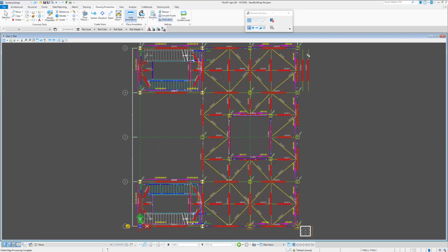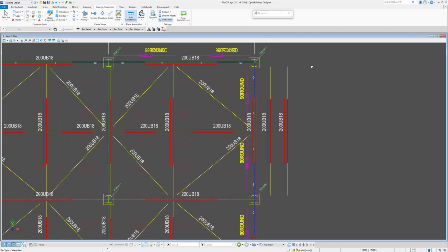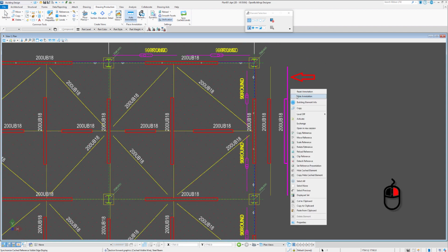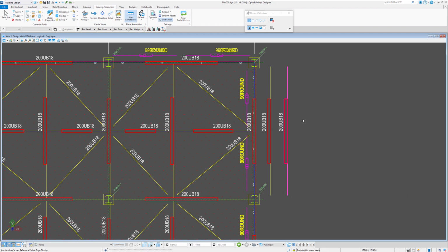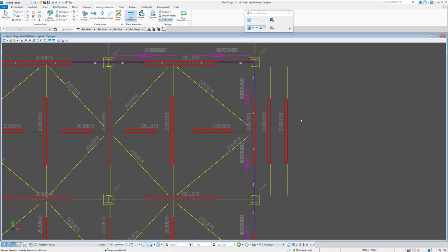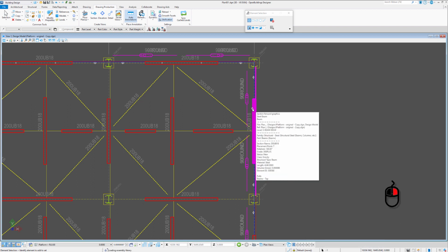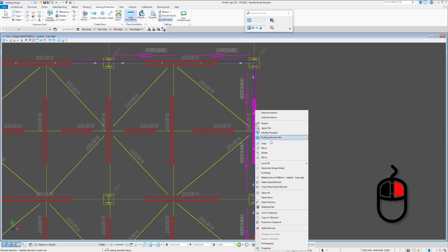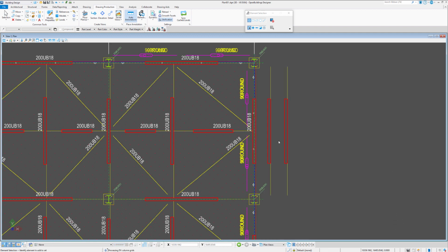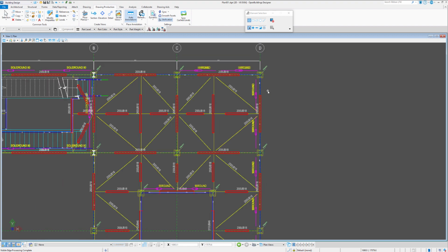So in our drawing model, let's have a look at these beams that we copied earlier up here. If I hover over these, I can hold right click down and say activate. And I will physically activate the 3D model and all elements in the drawing model itself. I can then choose to delete those beams. And then once I finish editing, I can then hover over again, hold the right mouse key down, and choose deactivate design model. Again, it then requires you to sync, and that drawing is now synchronized and the changes have been made.